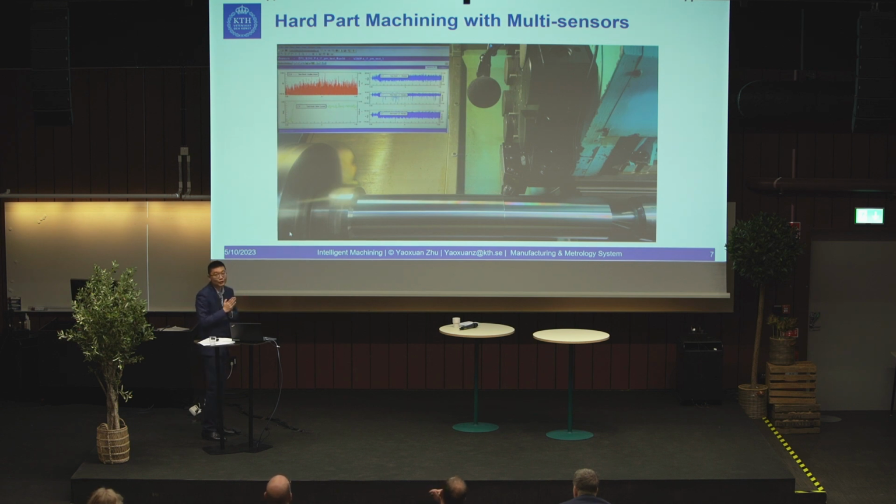And the green line represents the motor current of the spindle in the machine. But one thing I have to emphasize here: all the models or results are based only on the vibration signals. But in my real cases, I use all 3 of them, like a multi-sensor setup. Which means I use the sound, vibration, and also motor current to predict the model, and also to give the surface roughness.